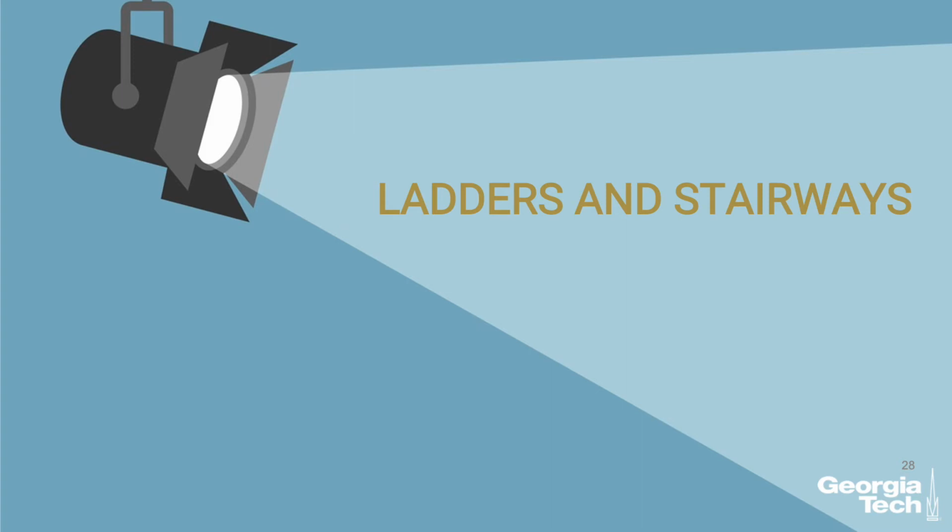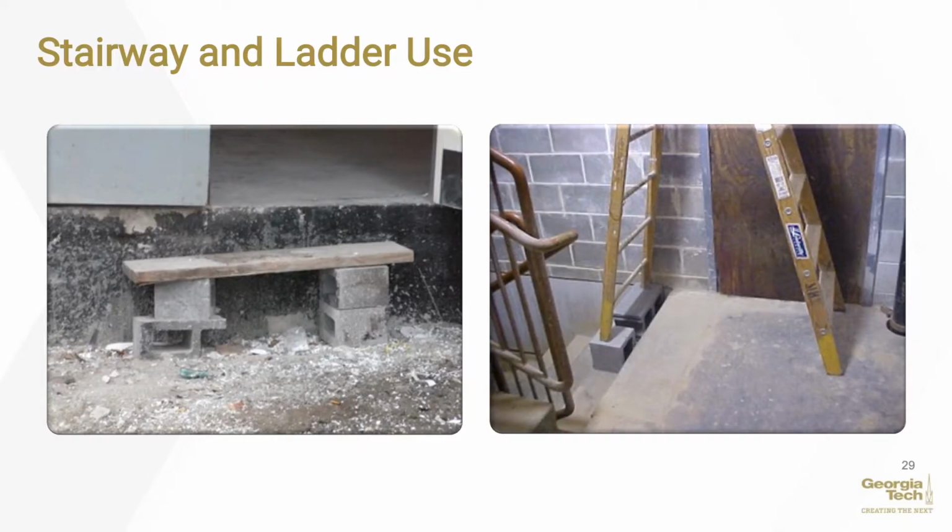Working on and around stairways and ladders is hazardous. Stairways and ladders are major sources of injuries and fatalities, and many of the injuries are serious enough to require time off the job. These hazards can be eliminated or substantially reduced by following good safety practices. When there is a break in elevation of 19 inches, 48 centimeters, or more, and no ramp, runway, embankment, or personal hoist is available, employers must provide a stairway or ladder at all worker points of access.